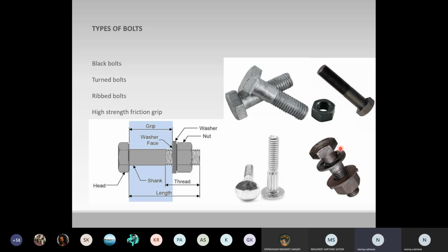So as we tighten the nut, after it reaches the width of the metal pieces, if we still try to give it a torque, it will create a tension in the bolt, which helps this friction to transfer the load from plate to bolt. Due to that, it has a higher shear resistance. It won't slice off due to the shear force or the loading.